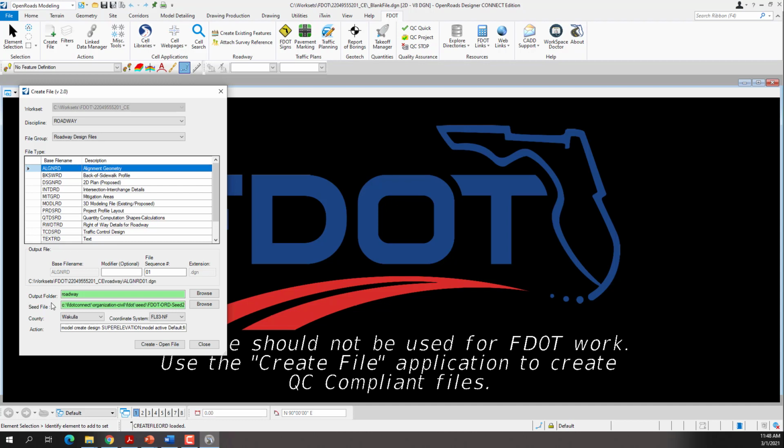That'll put us in the correct output folder, which is Roadway. The seed file, which we don't have to do, is -ORD. The county is Wakulla for this project. That will set our coordinate system.